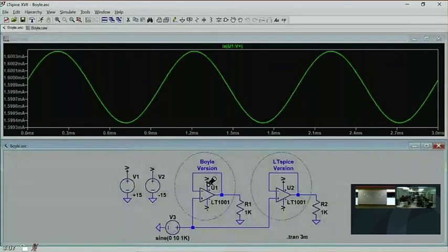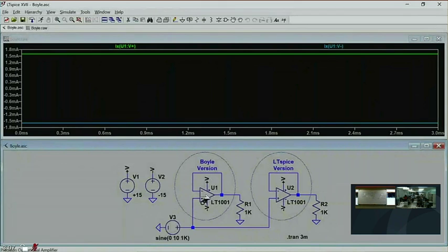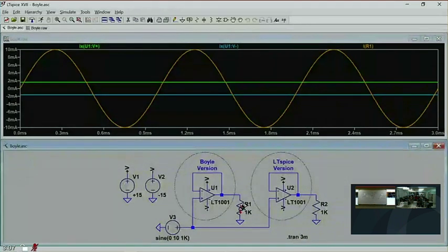This is the positive supply pin current and negative supply pin current. This data says there's 1.6 milliamps positive supply pin current and minus 1.6 milliamps negative supply pin current. Again, pin current sign convention is positive into the pin, so that data is telling you that there's 1.6 milliamps drawn through the positive supply and going out the negative supply pin. Good. So you look at the output current, 10 milliamps.